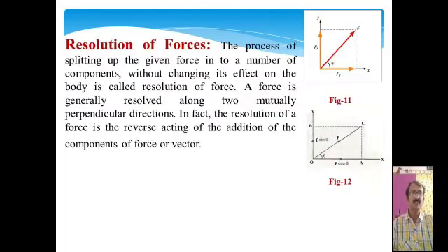In fact, the resolution of a force is the reverse of the addition of the component forces or vectors. In figure 11, it is clear that this is the force F. This force can be represented in the x direction, that is Fx, and in the y direction, that is Fy. In figure 12, Fx is F cos theta, and Fy is F sin theta, where theta is the angle between F and the horizontal axis x.